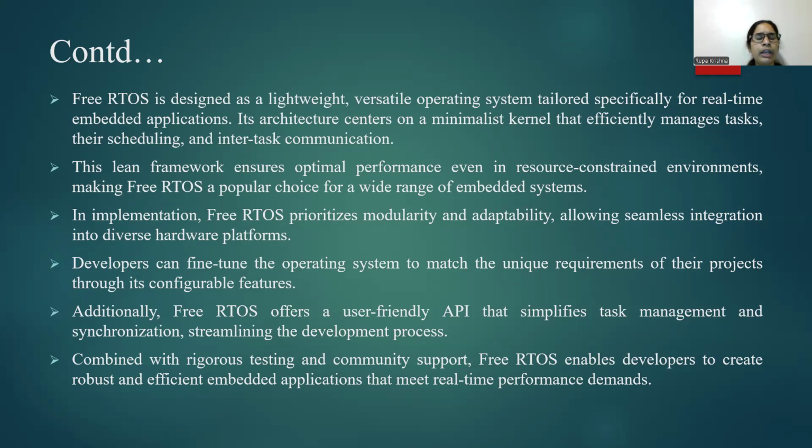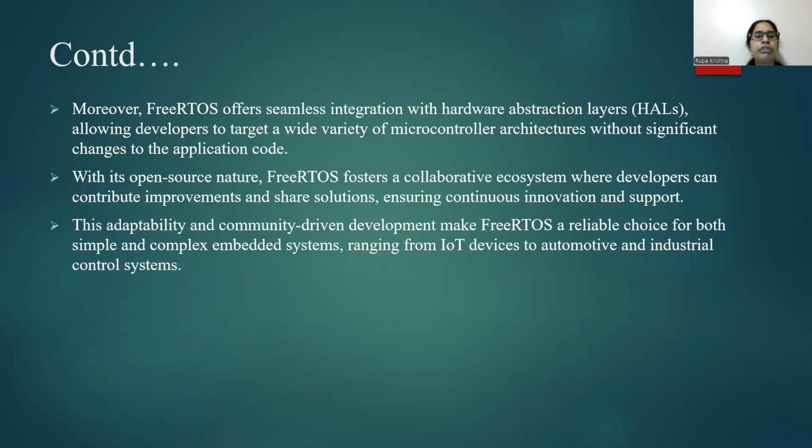Additionally, FreeRTOS offers a user friendly API that simplifies task management and synchronization, streamlining the development process. Combined with testing and community support, FreeRTOS enables developers to create robust and efficient embedded applications that meet real-time performance demands. Moreover, FreeRTOS offers seamless integration with hardware abstraction layers like HALs, which allow developers to target a wide variety of microcontroller architectures without significant changes to the application code.